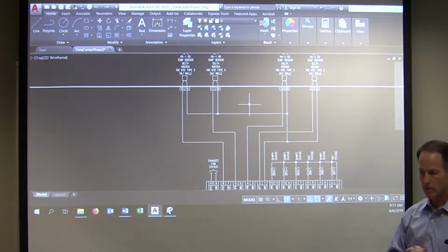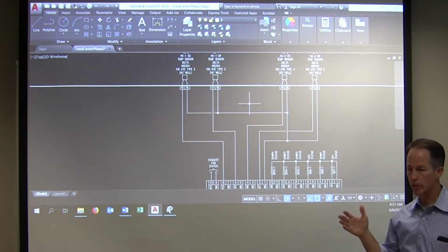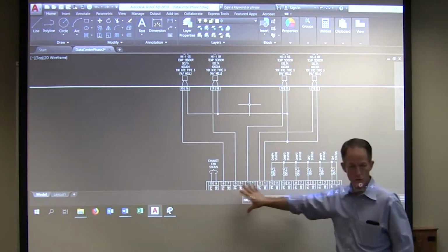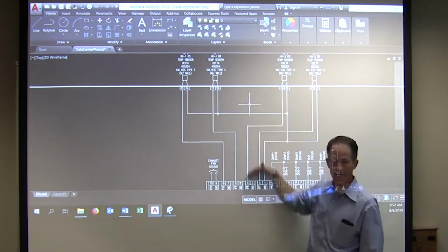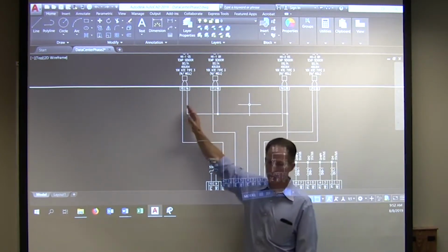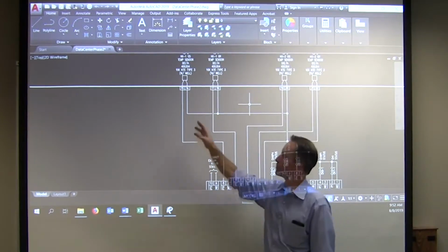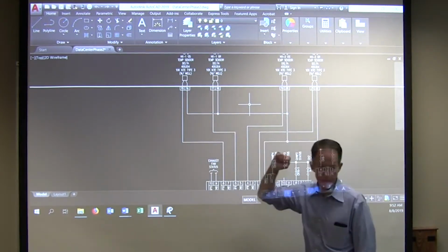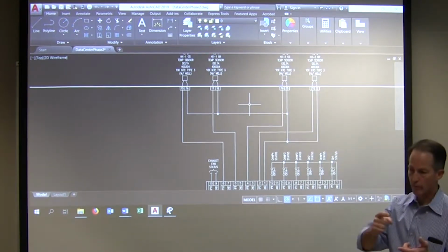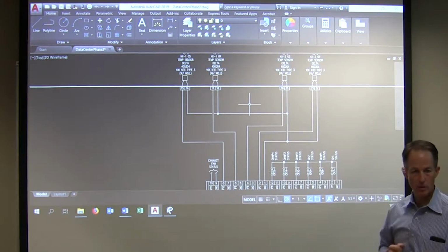Disconnect with 15 and 16. Okay, so most of you have all had an opportunity to do this. Because we don't know what this controller or anything here is doing to the circuit, we want to disconnect any interference or any outside influences. So I disconnect my wires at 15 and 16, and I put my meter on them. Do I turn to volts AC, volts DC, resistance, capacitance? What do I look at?